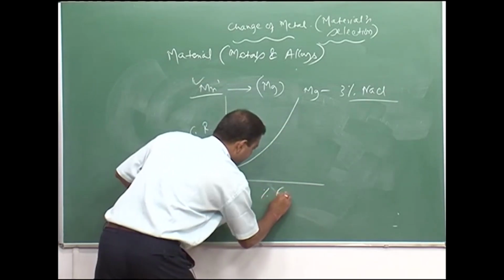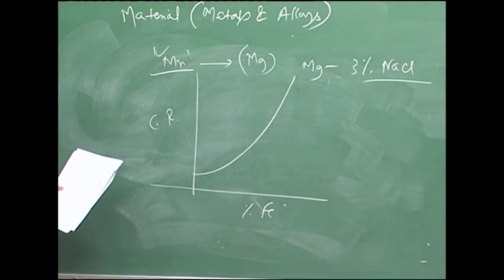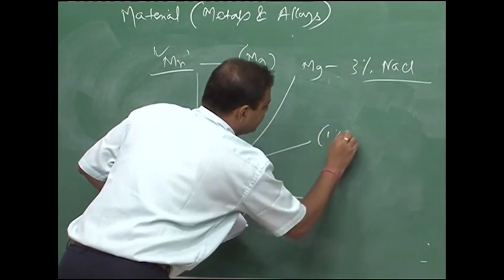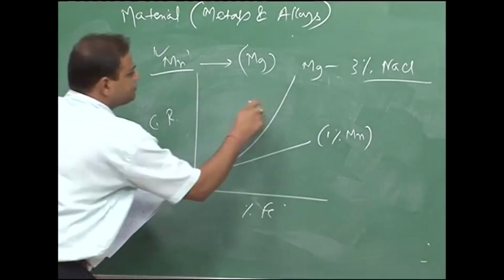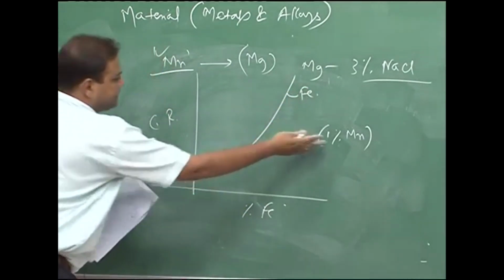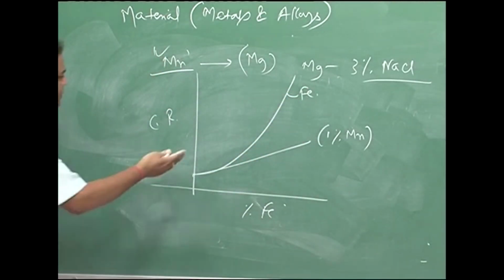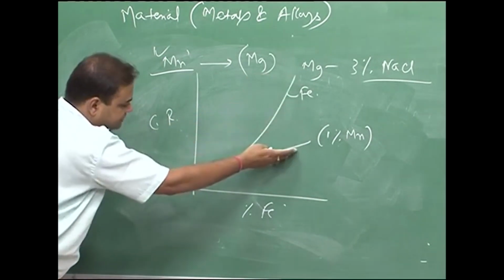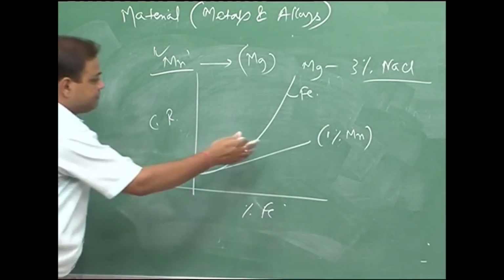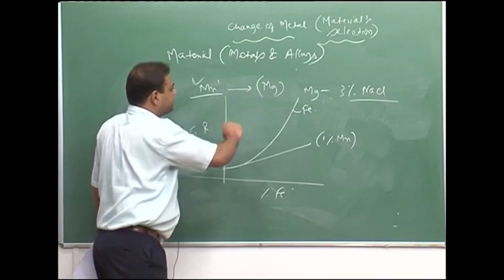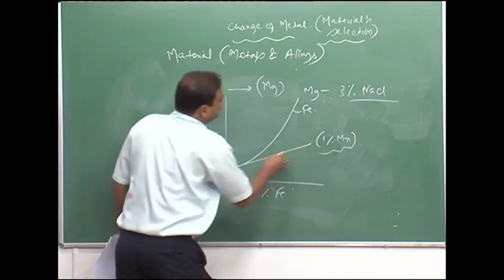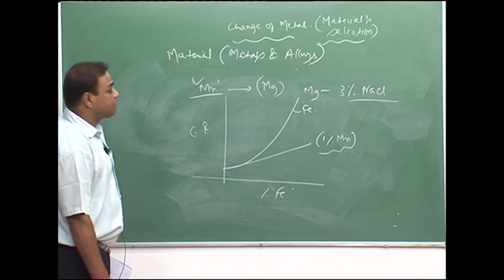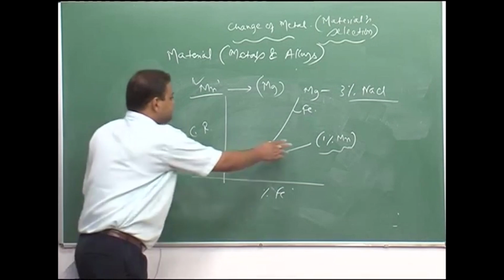This is the percentage of iron. Now, if we add 1% manganese, this is with iron only, and if we add 1% manganese, it improves the corrosion resistance of the material. So, corrosion rate reduces from this to this. If we have 1% manganese, it basically covers up the negative effect of iron. What it does, this manganese also increases the hydrogen overvoltage, or hydrogen polarization increases due to the presence of manganese.